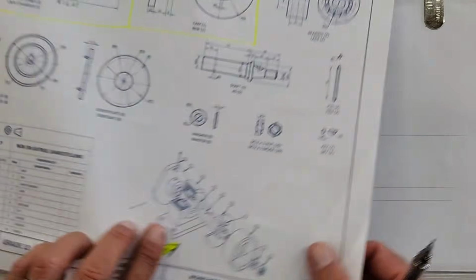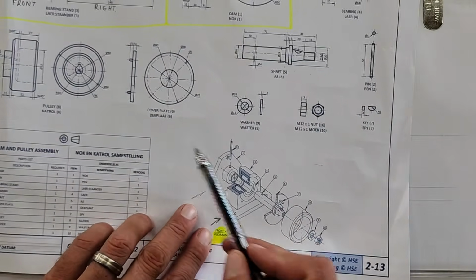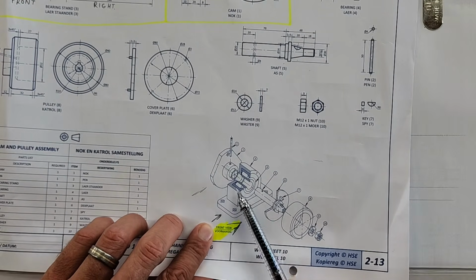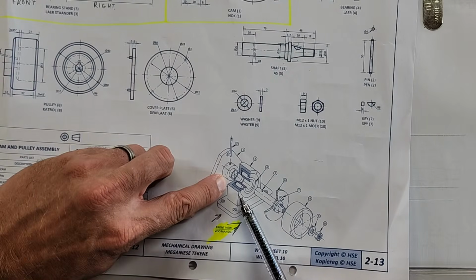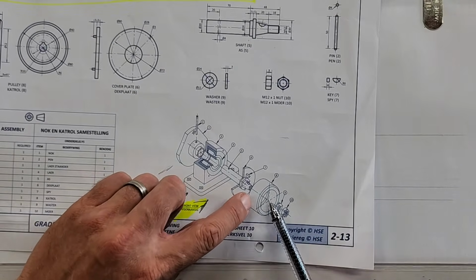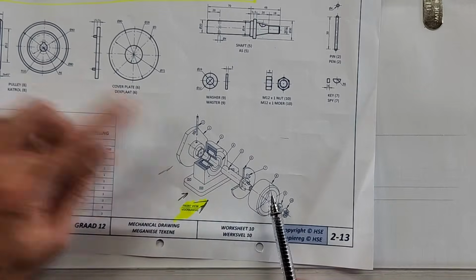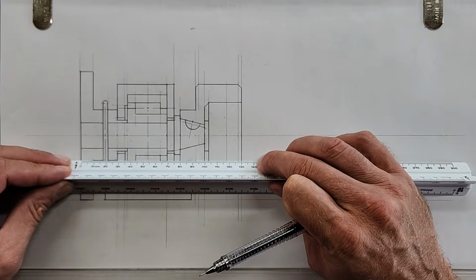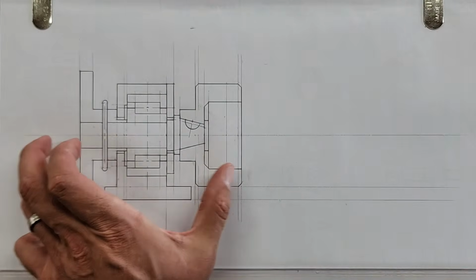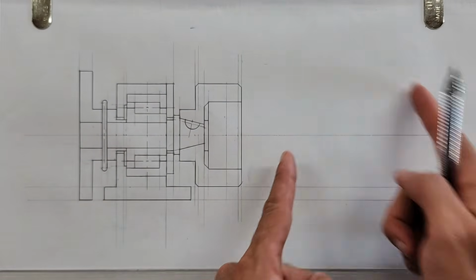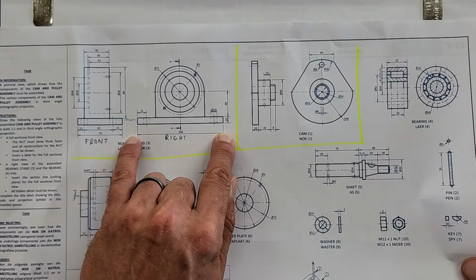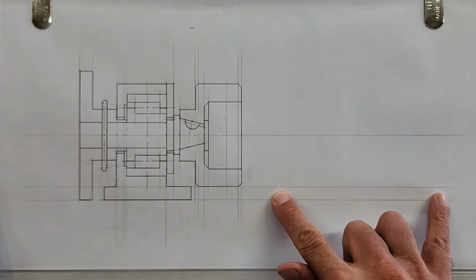Then I looked at the different parts and I saw, okay, I've got my cam here, its width is about 40, then I've got my bearing stand, then I've got the cover plate with the pulley. So in total there, I'm around about 130, 140 in width. I had to leave enough space on that side, plus leave enough space here, at least 100 for my right view. And of course, the longest part is 140 for that base. So I have to have at least 140.